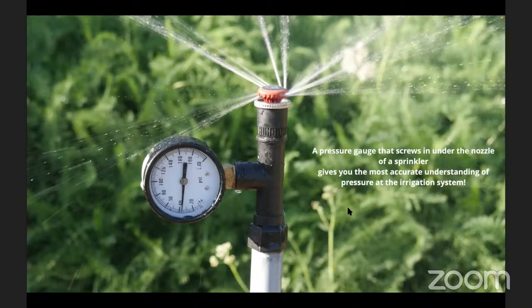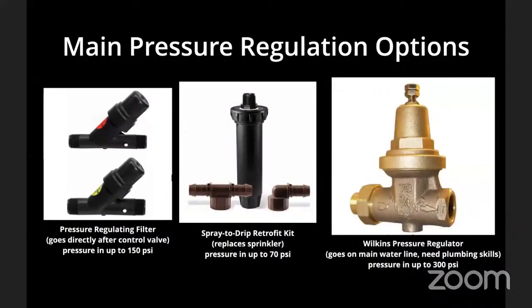It's a little complicated, but long story short, if everything seems to be working for your irrigation system and you already have the automatic valves, chances are you can just add on that style pressure reducer and filter. These are rated for an inlet pressure, the pressure coming into it, of up to 150 PSI. That's pretty high.